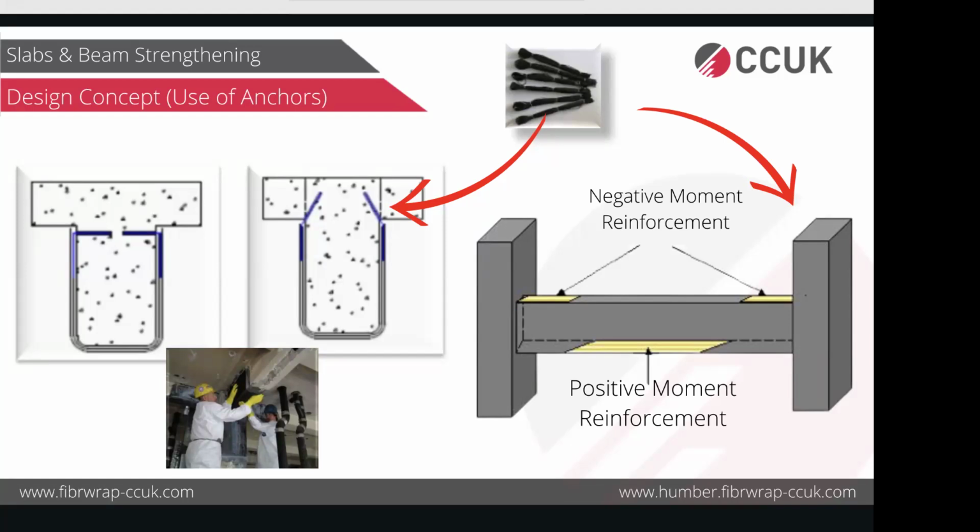The same principle works in traditional reinforcement as well. So in this case as well, there has to be some sort of anchorage detail provided in this situation. You can drill through the column, use the carbon fiber anchors going into the ends, or you can go up the column around it. So there has to be some sort of anchorage detail here.